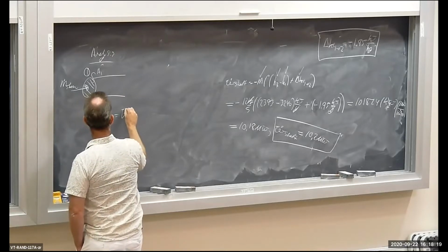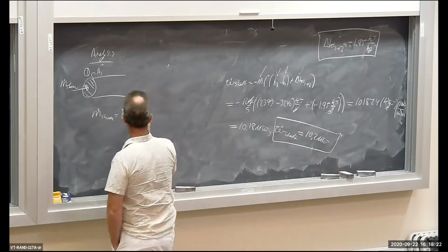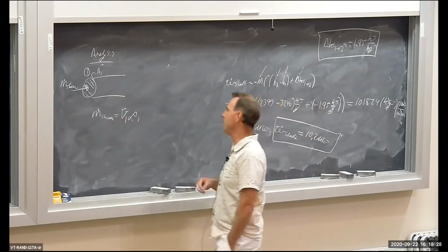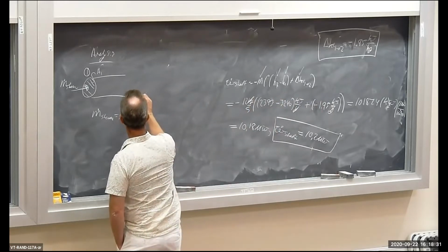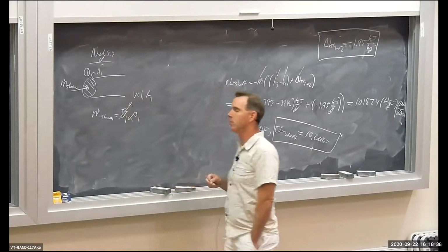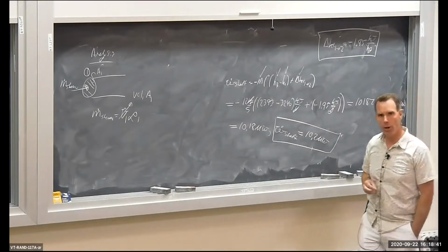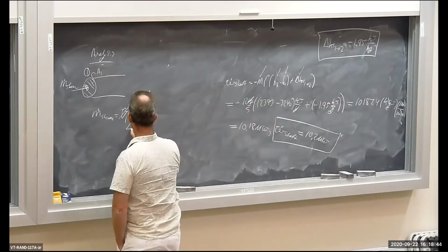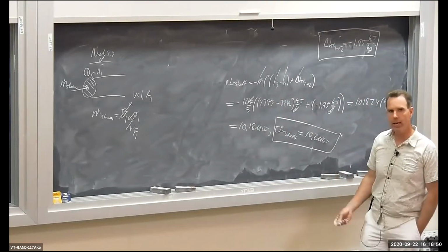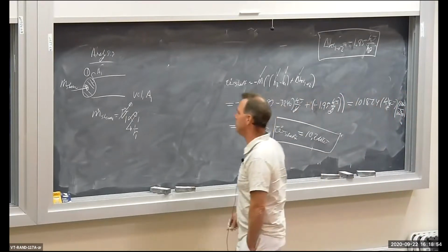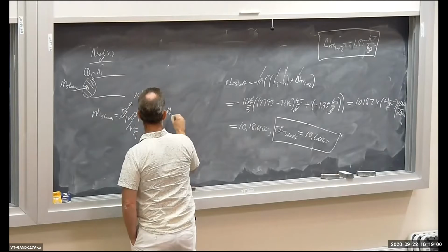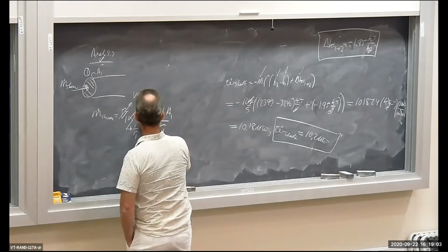So m dot for the steam is going to be equal to the volume flow rate at the inlet times the density of the steam at the inlet. So V dot rho 1. Now V dot is equal to the velocity at the inlet times the flow area at the inlet. And density is 1 over specific volume. Tables don't give you density, they give you specific volume. That's why I'm converting density into specific volume. So I have velocity 1, area 1, over specific volume at the inlet.